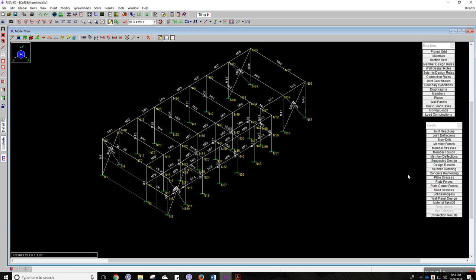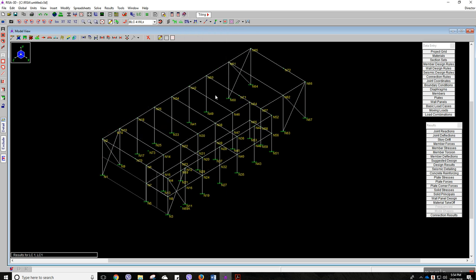So this video is already 35 minutes, so I think it will be better to make another video for getting the appropriate members for this design. Up to here, what we did is we gave the spreadsheet section set, we drew all the members, we applied boundary conditions on all the members, and at the ground level we applied the different loads: dead load, roof live load, snow load, and the wind load in x direction, and we solved the three load combinations.